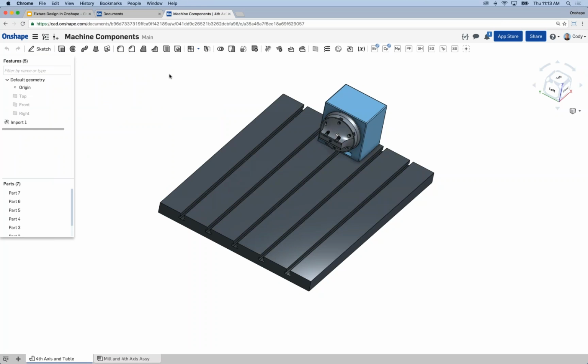And I would just construct a document consisting of all the standard things you work with: my standard vise, my standard clamps, my standard compound table if I'm doing those kinds of operations. Build all of that into a single document, and then you can reference it anywhere you want.